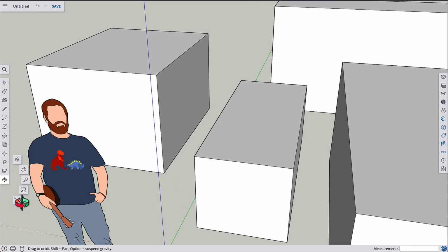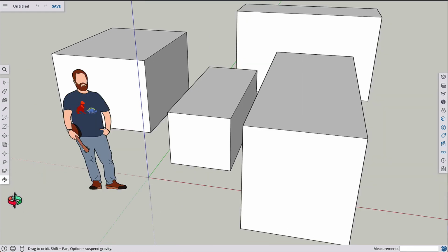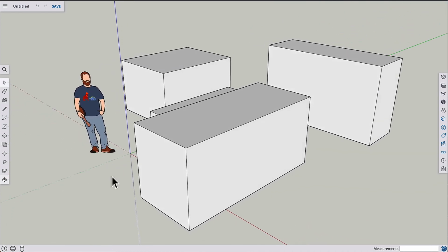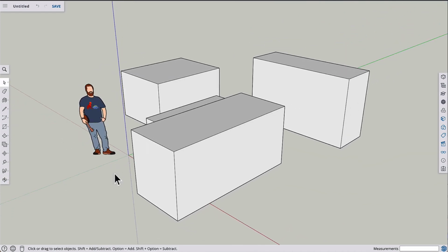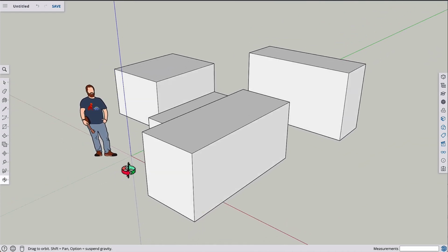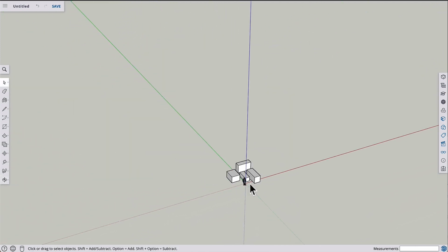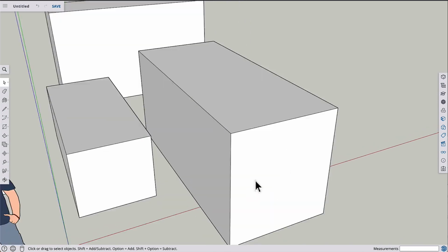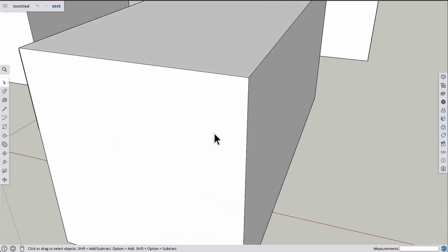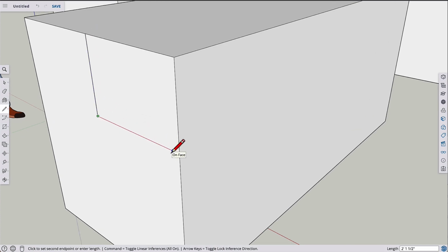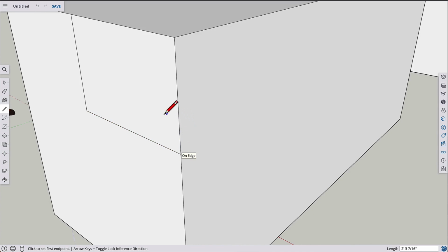That's basically it for navigation. Just be sure to practice so it becomes second nature to you. One common mistake for beginners who are still getting used to navigating is that you'll stay in the same view, often a distant view, while trying to draw or work on some details. Get up close to your model, get comfortable moving all around, and choose the best view for whatever action you are trying to take.